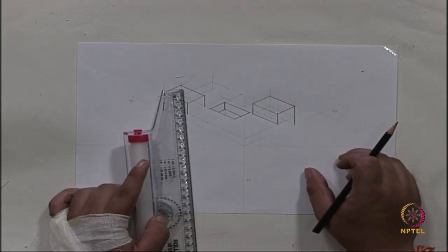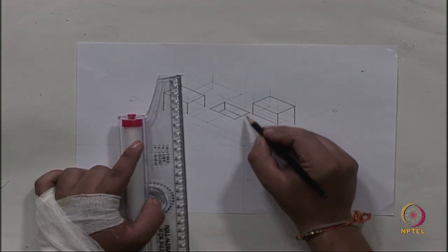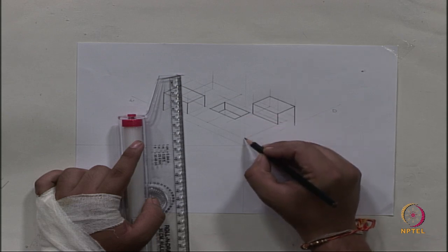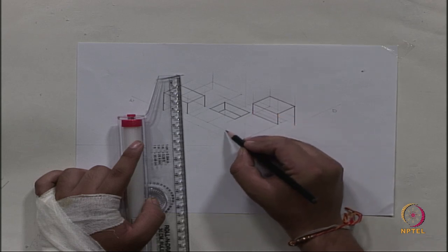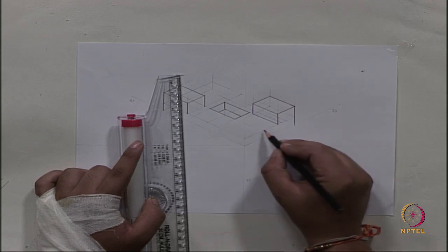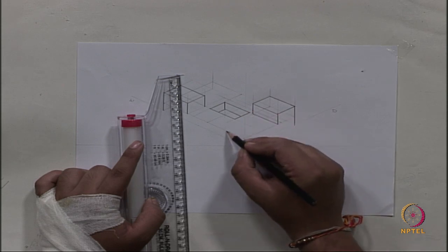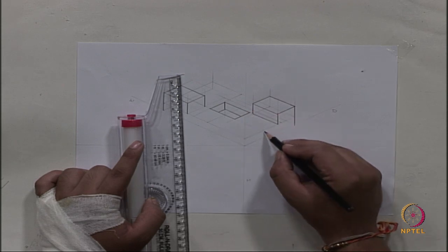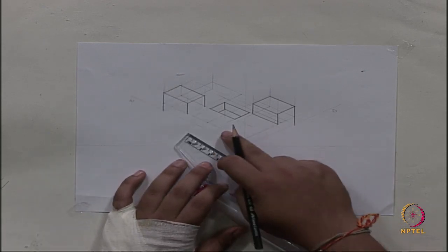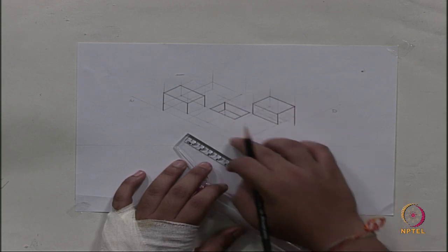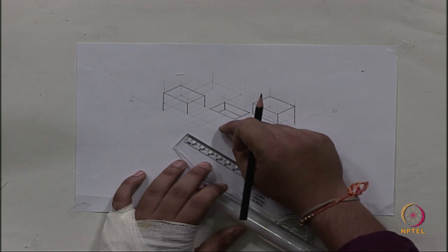In the 4 center method, we will first identify the short diagonal and draw lines using the end points of this short diagonal and the midpoints of the two opposite edges. For that, I need to first locate the midpoints of these two edges. Since I need not draw the full circle, I will locate the midpoints of these two edges only.